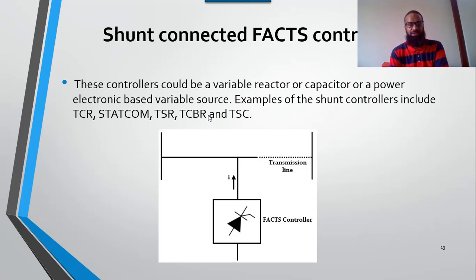Among these four controllers, the commonly used controller is the series-shunt controller, because in the series controller we have to design it with the capability to control all the currents. As you know, in the series circuit, the main current flows through the circuit, so our capacitors, inductors, rectifiers, and thyristors are specially designed based on that current.